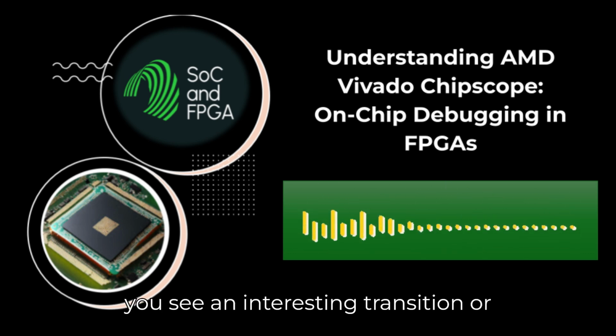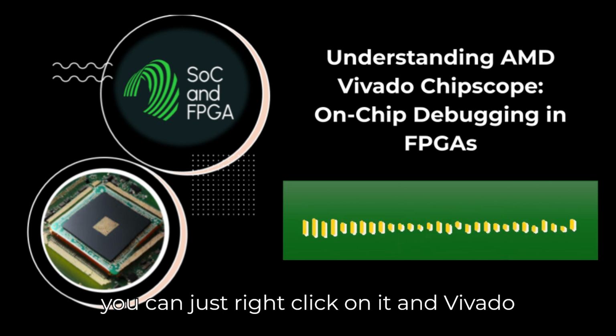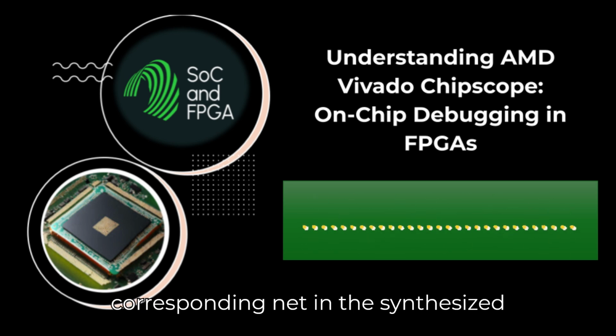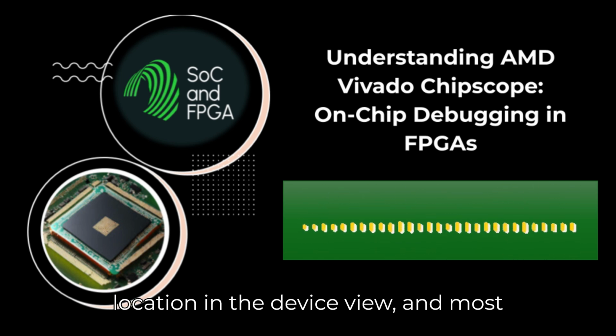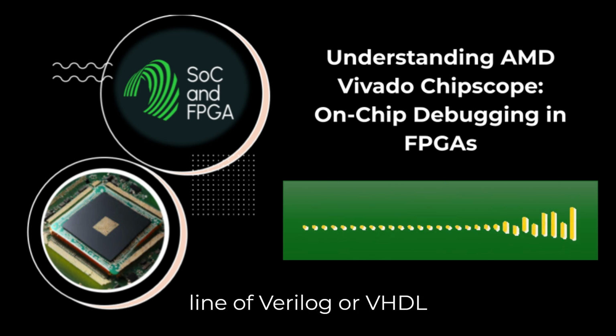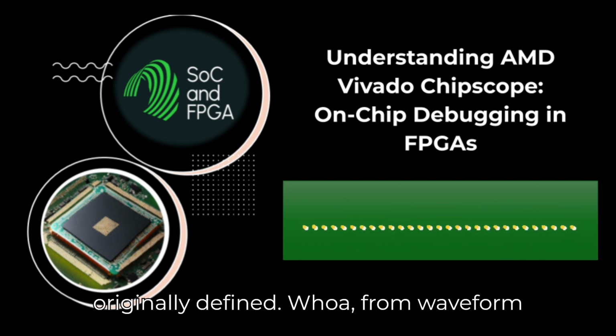If you see an interesting transition or value on a signal in the waveform viewer, you can just right-click on it. And Vivado will instantly navigate you to the corresponding net in the synthesized netlist view, show you its physical location in the device view, and most importantly, jump you directly to the line of Verilog or VHDL source code where that signal was originally defined.